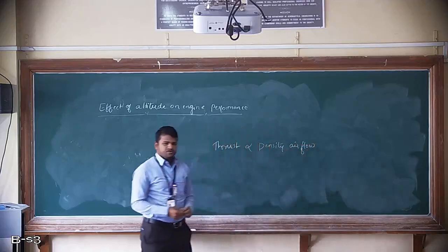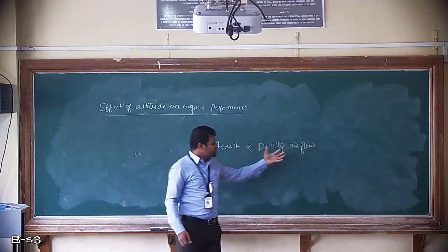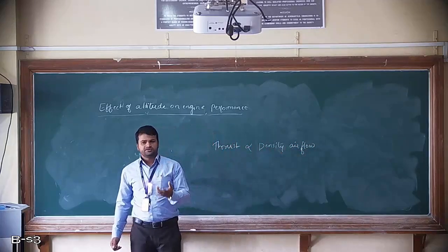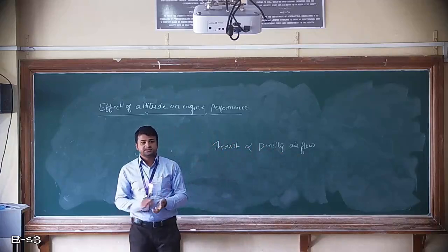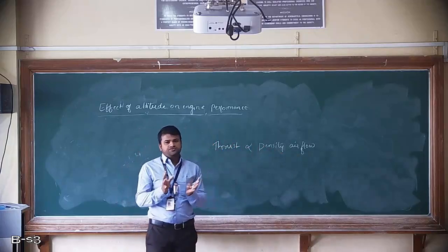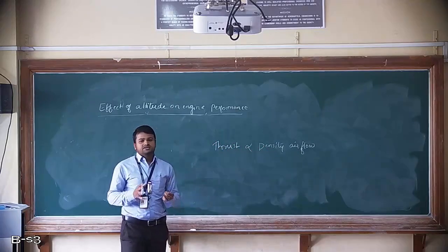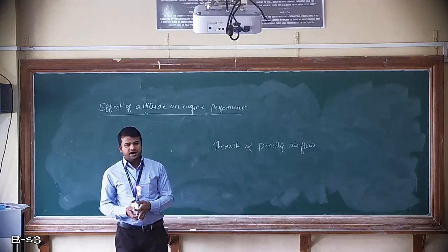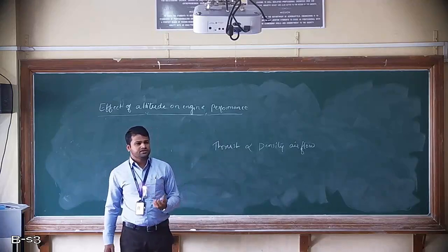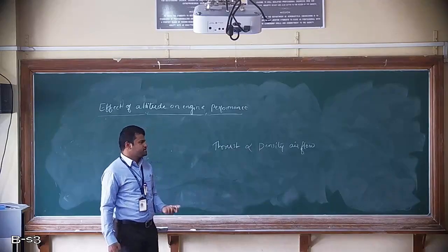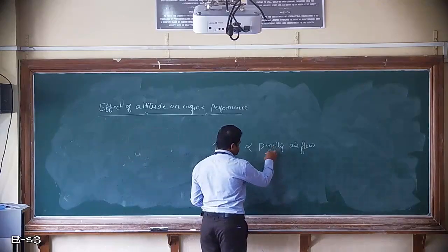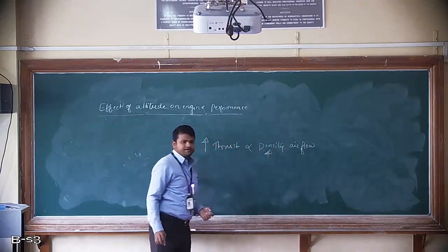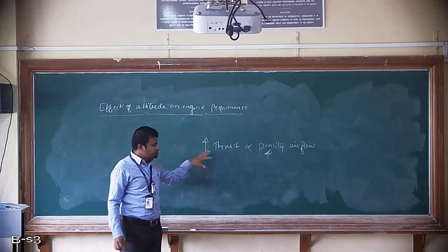Because if we have a high amount of airflow, the mass flow rate of air going inside the engine is more. That means it will produce more combusted product or hot gas, which in turn goes out through the nozzle and produces the thrust required for the aircraft. So higher density of air means more thrust. This is one of the good performances.